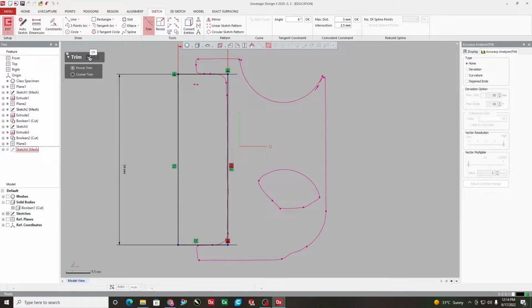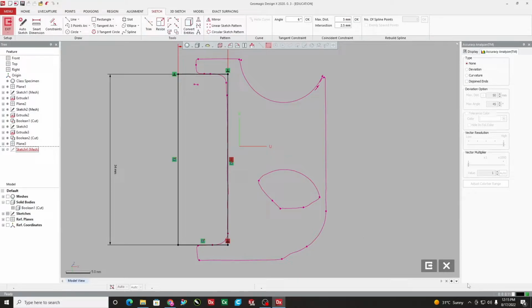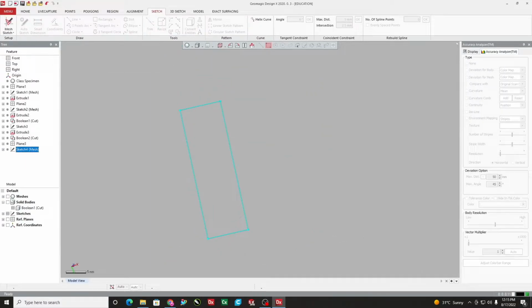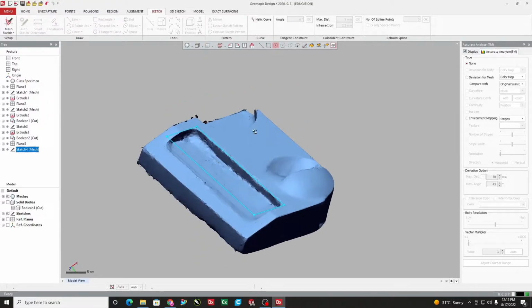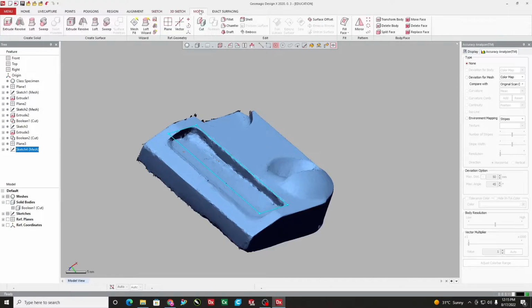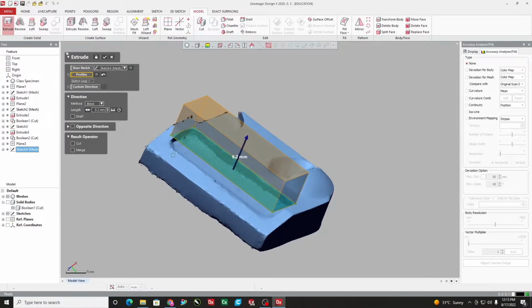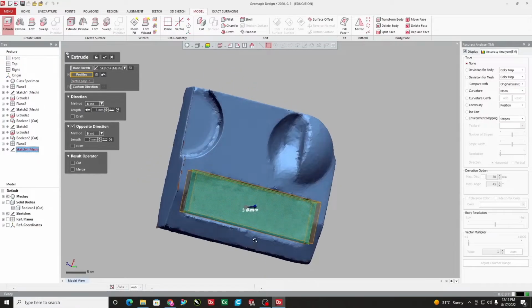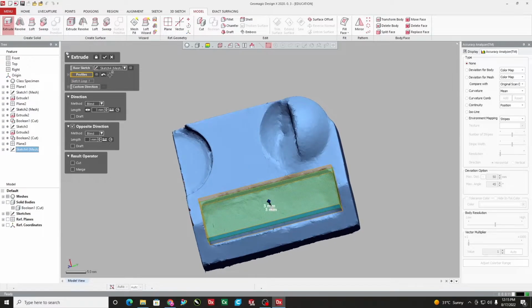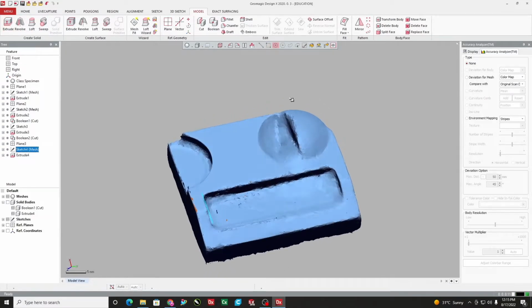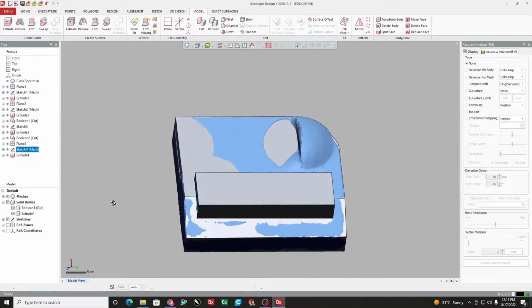So again we'll come to model options, the model tab. We'll try to extrude so that we create one tool and the main body remains as our material. That is cut, and we get this pocket in the model. So now this is created. In the model, it is extruded out, and down there the side is 3 mm. So it becomes my tool, my base object becomes the material,